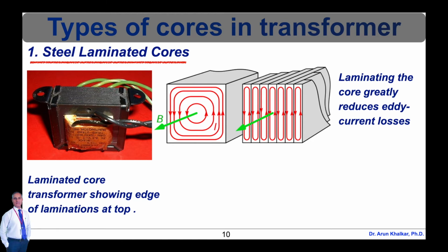flux. The effect of laminations is to confine eddy currents to highly elongated paths that enclose little flux, and so reduce their magnitude. In the figure on the left, eddy currents I, in red color, flow within a solid iron transformer core.